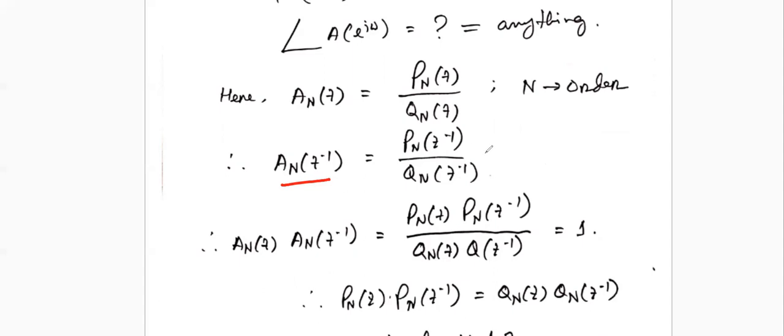And this is very simple, because whenever you switch over the pole locations and the zero locations, it will help you to design the opposite type of filter. For example, let's say this is the unit circle, and you have a zero here, and you have a pole here. What kind of filter is this? Low pass or high pass? Low pass. This is a low pass filter.